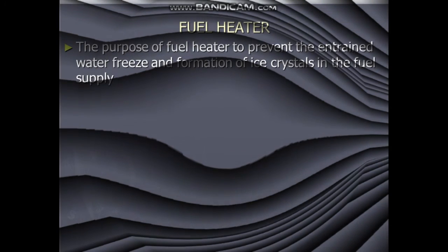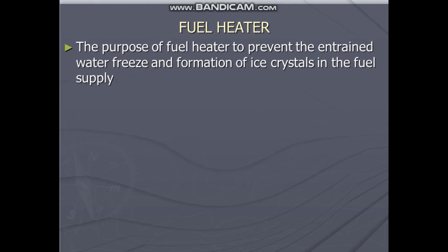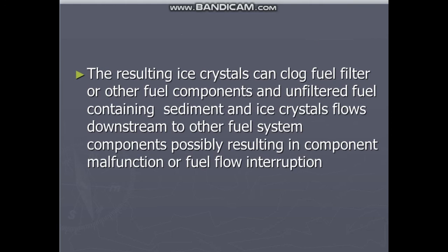Fuel heater. The purpose of the fuel heater is to prevent entrained water from freezing and forming ice crystals in the fuel supply. The resulting ice crystals can clog the fuel filter or other fuel components, and unfiltered fuel containing sediment and ice crystals can flow downstream to other fuel system components, possibly resulting in component malfunction or fuel flow interruption.